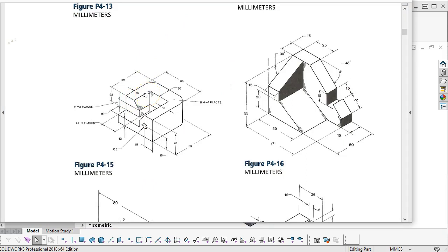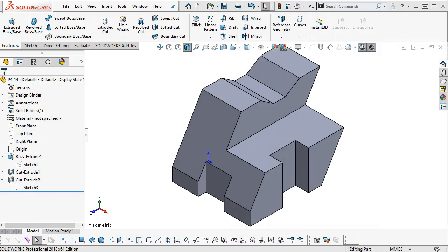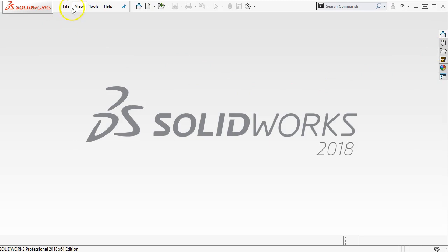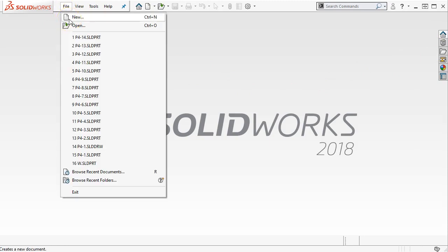Interesting chamfer manufacturing-wise. This comes back to Sinker EDM to get that to be sharp, or a lot of 3-axis work to make a very minimal radius in that corner. That being the case, we'll take a look at what it would take to machine it or to increase the manufacturability.